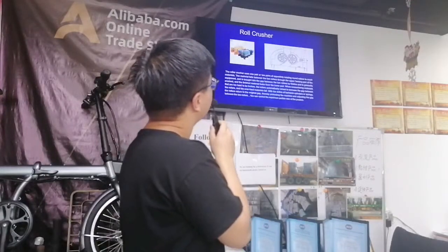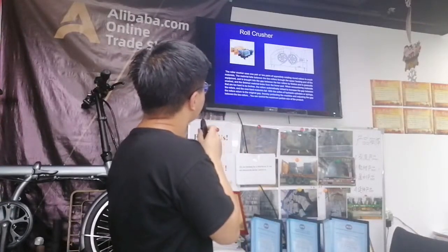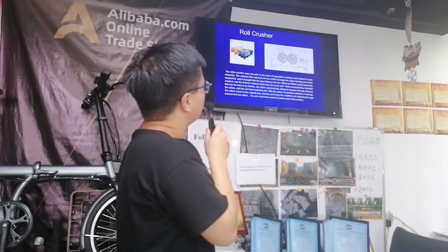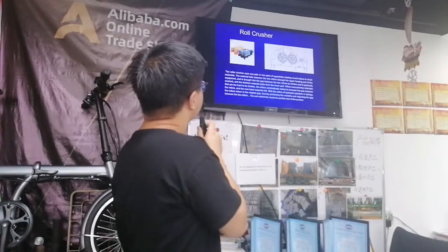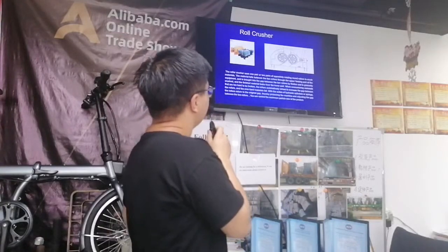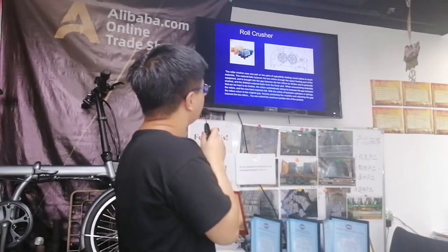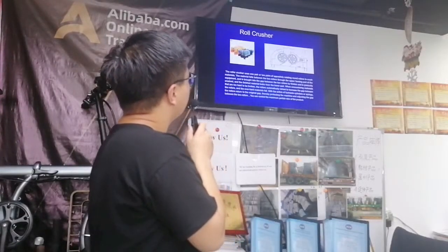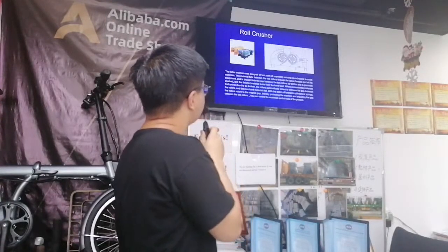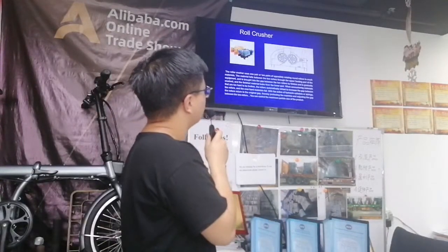When encountering materials that are too hard to be broken, the rods retract to increase the gap between the rods and the overhard materials fall. With the action of cylinders or springs, the rods return to the original gap, thereby protecting the machine. By adjusting the gap between the 2 rods, you can control the particle size of the product.